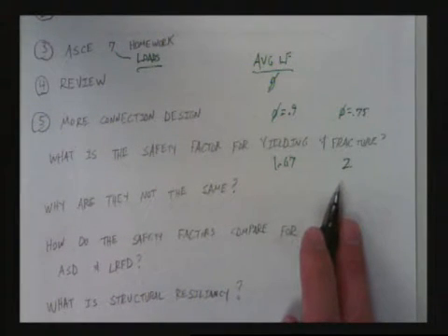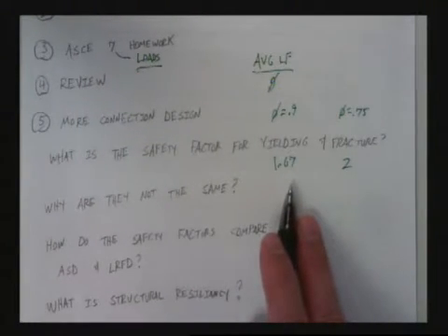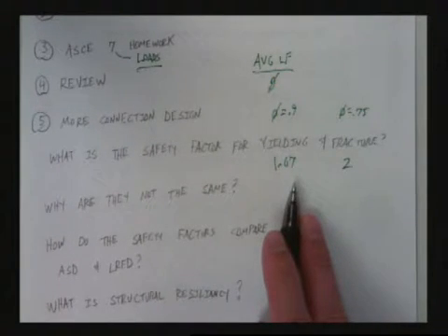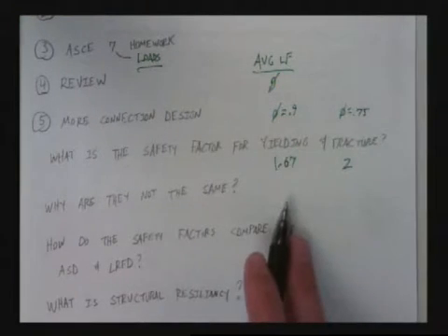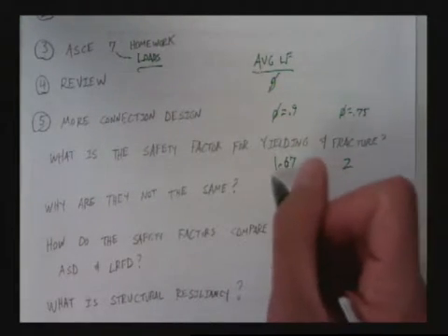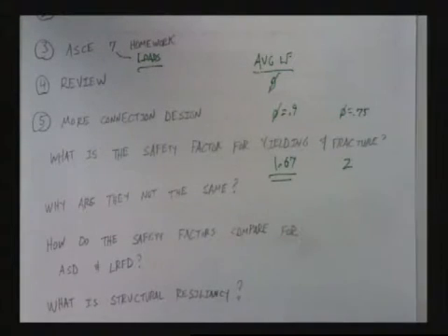I'd argue that when something fractures, you better jump, right? And when things yield, you can still survive sometimes, okay? You often can survive. Yield is not a hard number that we have to hit, but fracture is something we better respect, right? So that's why we're able to get away with less fat in our design on yield than with fracture, okay?